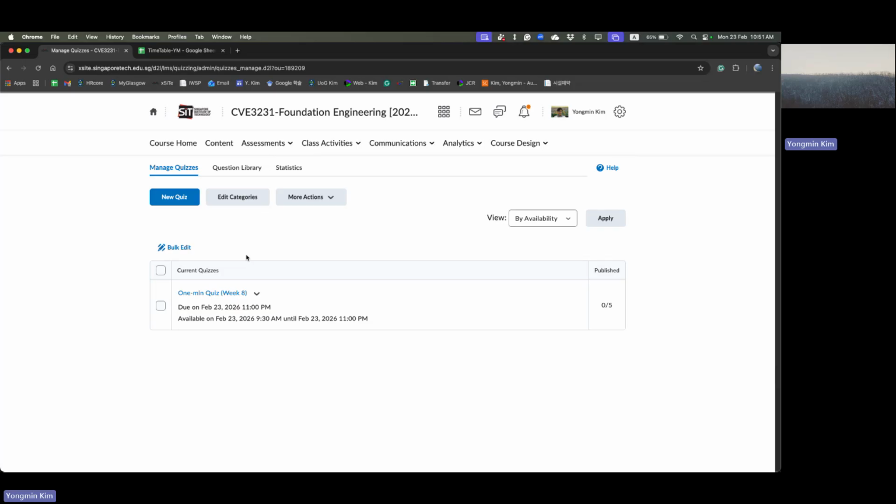What is the most common friction? Because normally we expect rock socketed piles, it means high end bearing capacity, but due to lack of the site investigation reports, sometimes we lost our end bearing capacity. That's why we only consider shaft friction only. Of course, we consider end bearing and skin friction, but at the end, we check shaft friction only. That's why most